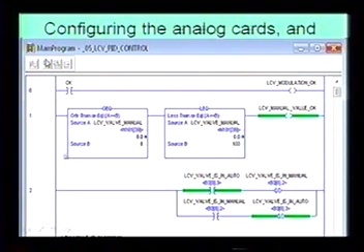If I put it in manual mode, that would be just in this case, you can actually rock it. So it's in manual. So unlatch your auto. If you're in auto, unlatch your manual. And so if you're in manual mode, then send a value. Here we have LCV, level control valve in manual, and it's got an alias N101 in brackets 39.